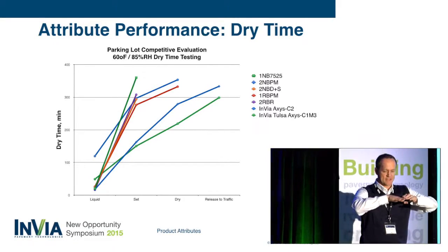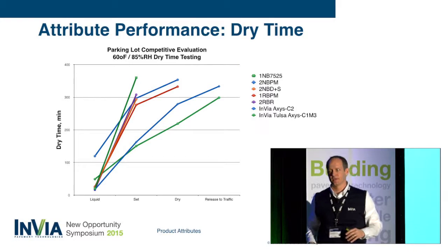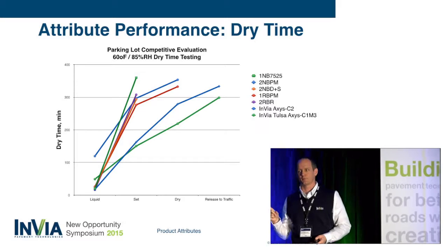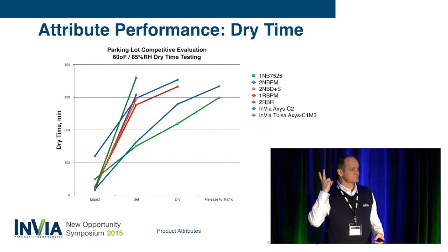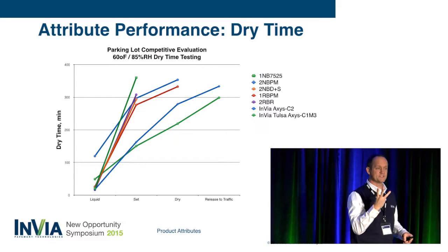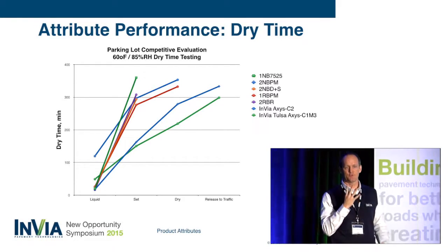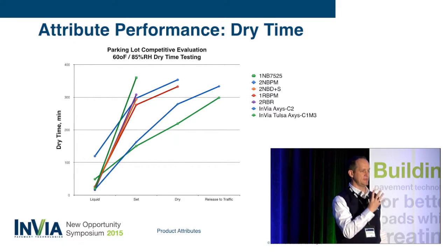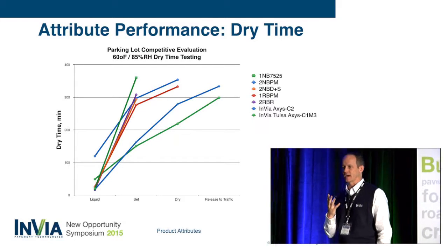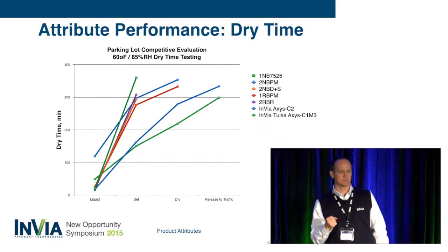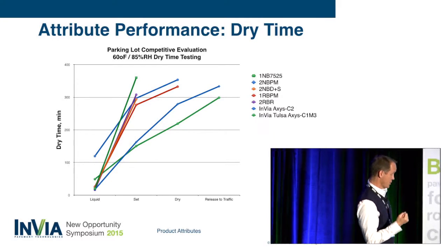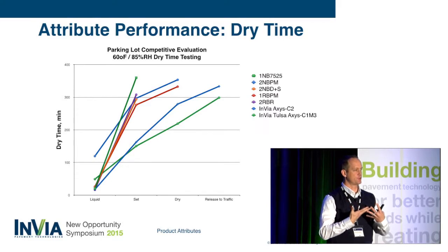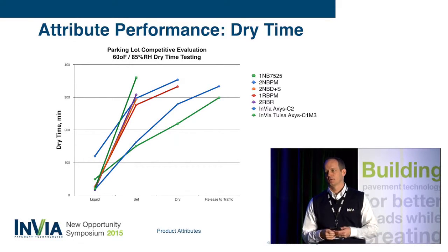And I'm talking about once you just have water on the top, you have the air-water interface. It is the surface temp, which is the pavement temp. If you guys have an IR gun, you can shoot it and know that number. It's the air temp. Look at your phone, everyone has air temp. Wind speed and relative humidity. If you know those 4 variables, you can plug them into an equation and you can know to the minute how fast a puddle of water of any given size is going to dry. And so the race to drying fast and curing as well is how fast that system can move the water out to the surface to be wicked away.